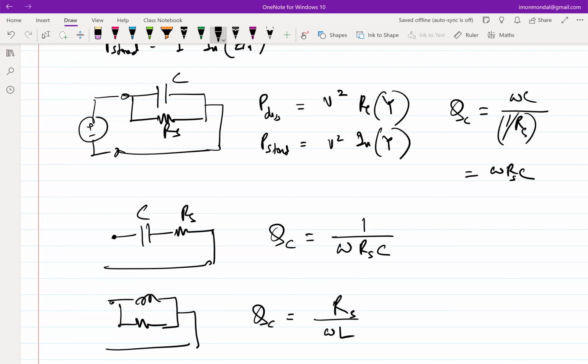Similarly, when you are going at lower frequencies, and if you assume that series resistance with capacitor model, right? So in that case, obviously, the Q increases if you use a capacitor at lower frequencies. That's why you will see that as you go at higher and higher frequency in RF design, you see more generous use of inductors because they are more efficient in terms of loss. And if you limit yourselves to a gigahertz, couple of kilohertz or so, then you see more use of capacitors.